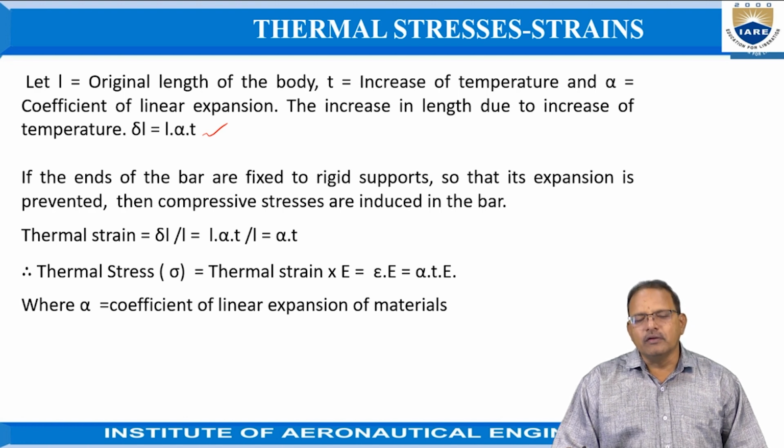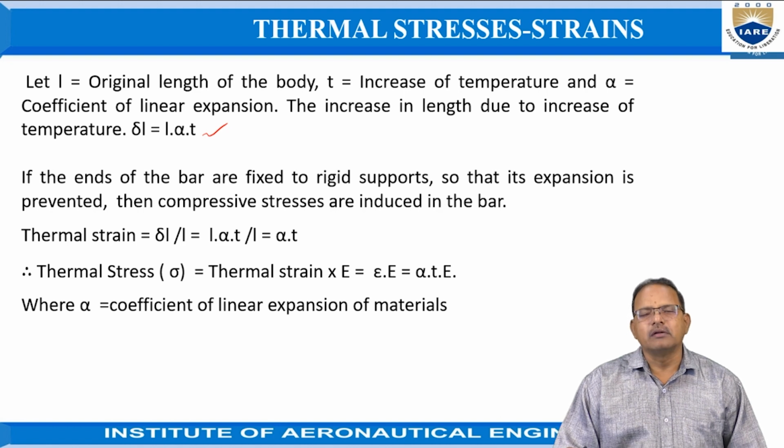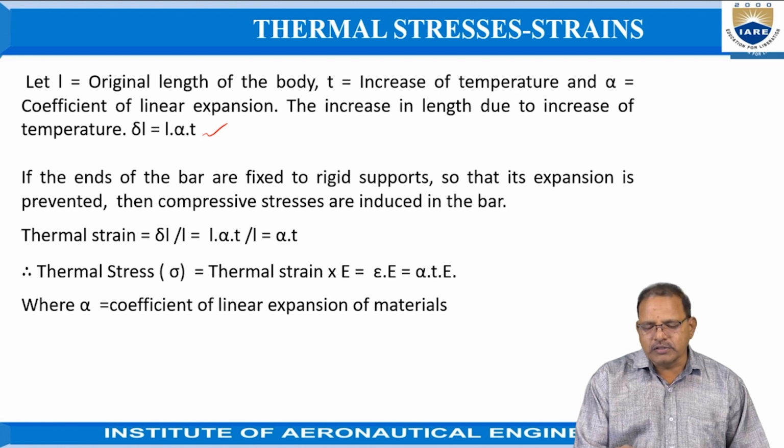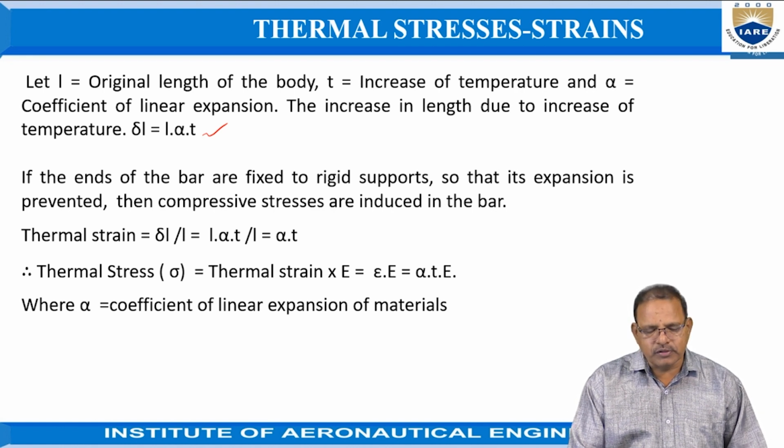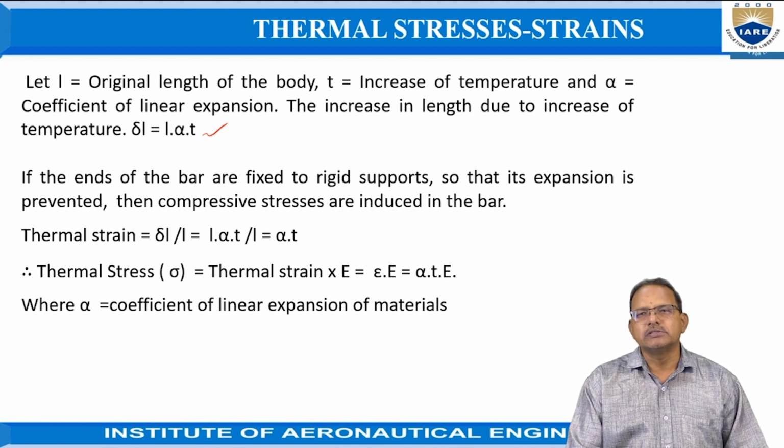This is when it is allowed to expand freely. But thermal stresses are induced in the body when the supports are kept to prevent its expansion as the temperature increases. Hence, when it is fixed between rigid supports, the expansion is prevented, so compressive stresses are induced in the bar.